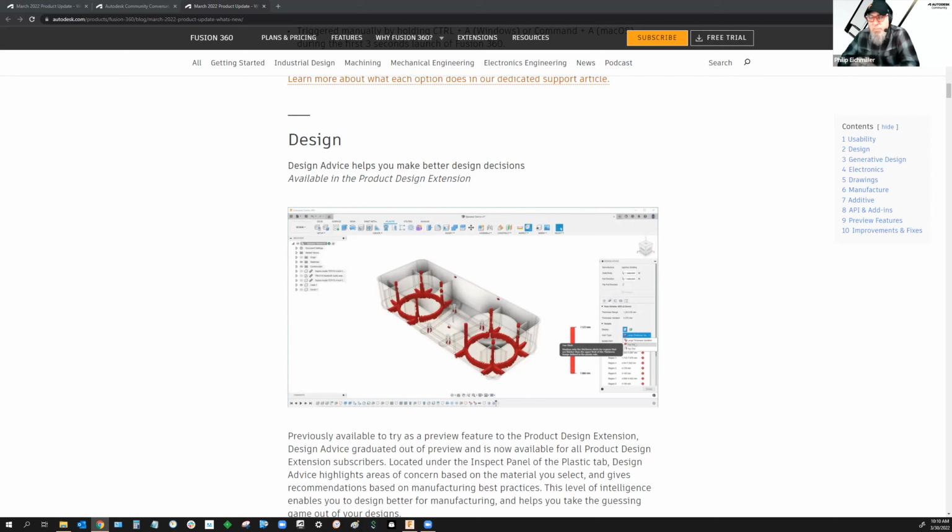Traditionally, before objects to cut, everything was based on visibility. Participation was always based on visibility. So for objects to join, if your extrude is passing through several objects and you don't want it to join with one of those objects, you're going to have to continue to use the visibility option and make something invisible in order to not have it participate in a join.